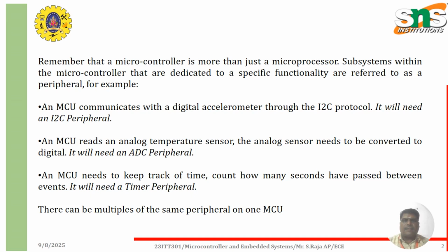Remember that a microcontroller is more than just a microprocessor. Subsystems within the microcontroller that are dedicated to a specific functionality are referred to as a peripheral. For example, if a microcontroller unit communicates with a digital accelerometer through the I2C protocol, it will need an I2C peripheral.